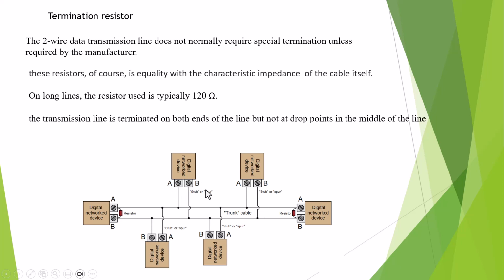Okay, this one, all the system looks like this: RS485 and Profibus always have a termination resistor at the start and at the end.